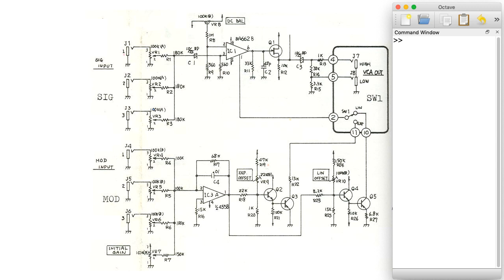Here I've pulled up Octave, which is like an open source rewrite of MATLAB, more or less. So technically speaking, I would have a 560 ohm resistance in the numerator. Then I would have 180 kilo ohms. So I'm writing E3 here. So that's 10 to the power of 3 plus 560. So yeah, that's a lot of attenuation. Whatever voltage is coming in, you'll only be getting 0.3% out. That's assuming that that volume knob is turned up all the way.